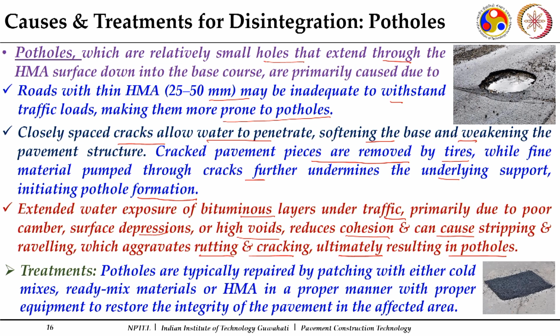What can be the suitable treatment? The important part is that the affected area needs to be carefully marked and the material has to be removed. Thereafter, nowadays we have a good amount of cold patching mixes. We have certain ready-made mixes also which can be stored for a longer period of time, and if the weather permits we can go for hot mix asphalt also. The pothole needs to be properly prepared, and we have suitable equipment to fill up these potholes with these patching mixes, cold mixes, and then it needs to be compacted so as to match the existing surface. So this is how pothole patching can be done.